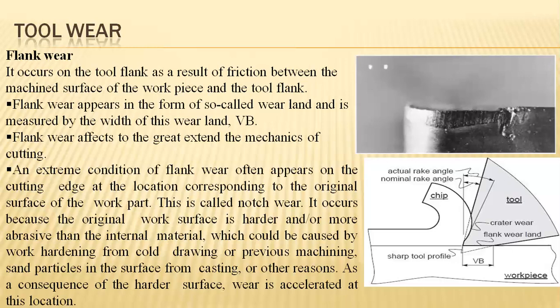And moreover, at this point of cutting, the surface cracks will be maintained and they even pass through the subsurface levels of the material in the form of notches. Hence, that is called notch wear. So it is the condition that will be arrived at because the work surface will be much harder and more abrasive than the internal layer of the same material, which is caused by the work hardening during the machining process.